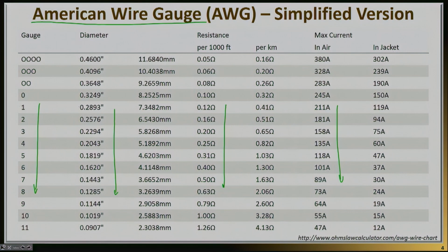So a lot of times we will see how much current we need, and we will give a safety factor to ourselves, and that means we will select the right gauge. There are many different factors that will influence your selection. For example, it will be influenced by the temperature of the environment that you plan to use this in. But in this case, I don't want to go through those details. All I want to alert you to is that there is a guideline that links the maximum amount of current that you need to transfer to the specific diameter of the conductor, given that you have chosen the material.